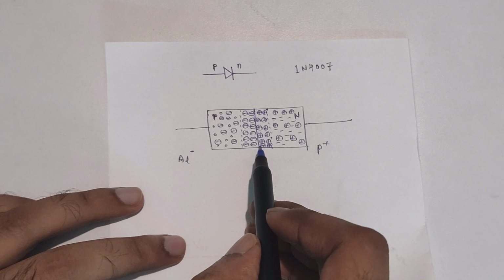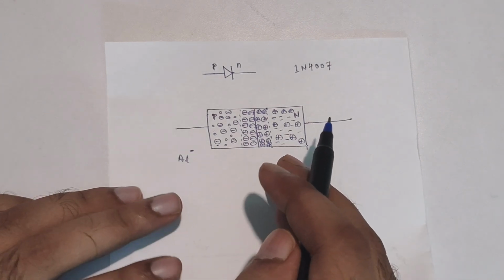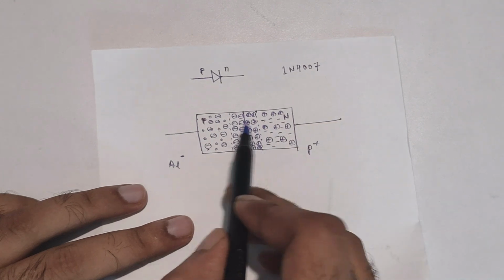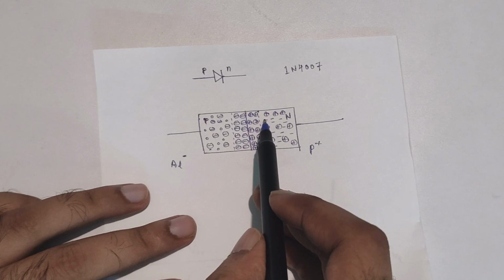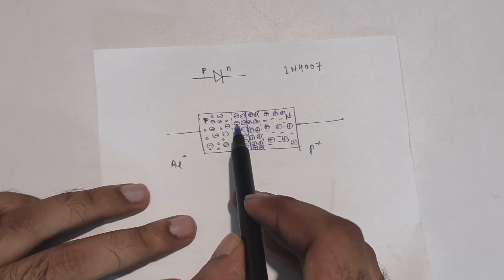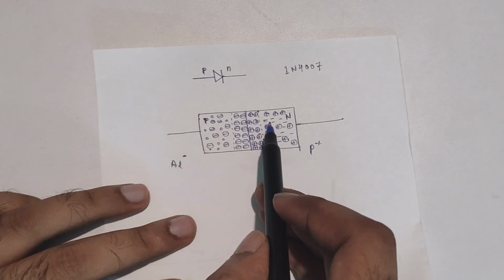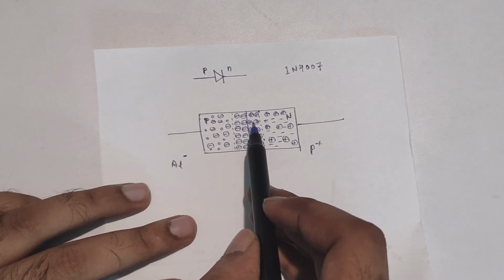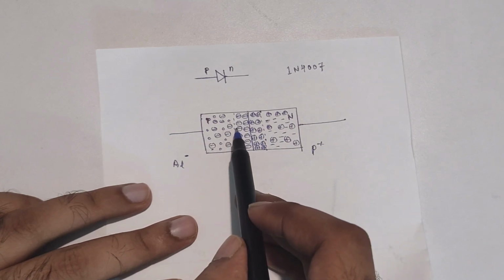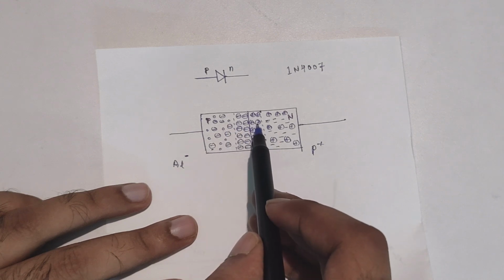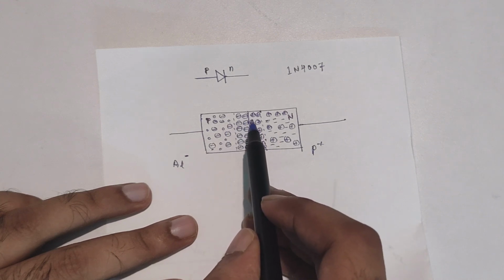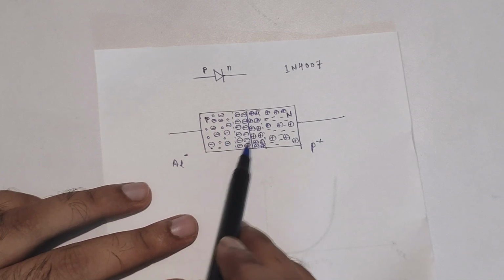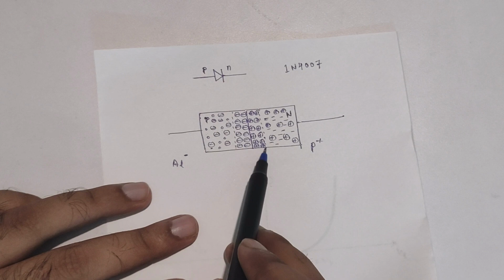Now in equilibrium, what happens when you join these two substrates? Actually we don't join them, but let us assume for the sake of simplicity that we join these two substrates here. What actually happens is that electrons drift into the P substrate and holes drift into the N substrate. Because of that, the electrons and the holes recombine with each other, but the ions do not actually react. So electrons and holes when combined become neutral, but the ions remain charged, and because of that, in the depletion region that we can see here, I have shown the depletion region by dotted lines. So this is the depletion region that you can see.